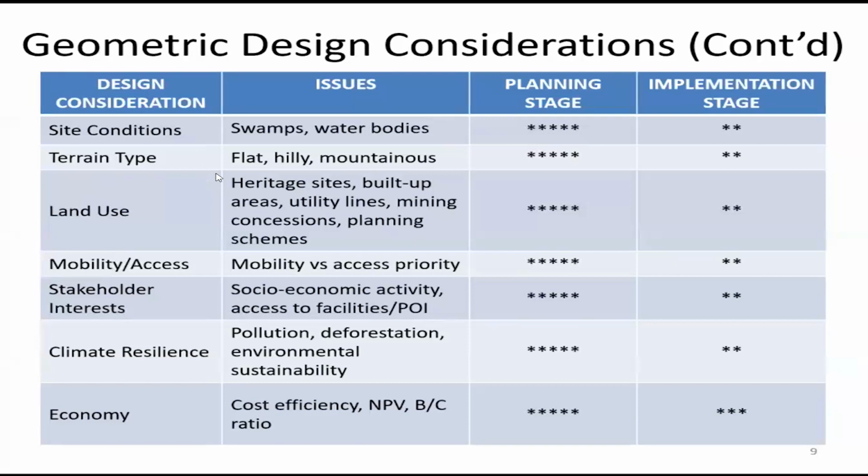On active projects, you may have to look at the geometry once again as a way of avoiding or managing utility lines. You either avoid them completely or you shift your center line and other things such that probably they fall under pedestrian walkways where that can be done.